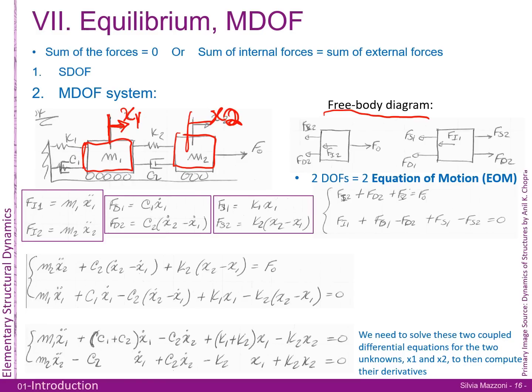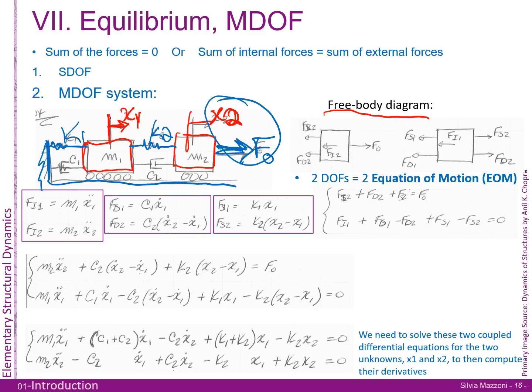Now, in this example, we've got a number of different springs and dashpots. So we have a rigid wall, very important, and then we've got a spring here between this mass and the wall, and a spring here that connects the two masses, okay? And they've got different spring coefficients, of course, because that would be too easy. And the same thing with the dashpot, okay? Makes it a lot easier because we can solve for K's, then we can do the same thing with our dashpots. And then we have an external force, F0. This force is only applied at this degree of freedom, and there are no forces applied here. You may see examples where you actually have a force at this degree of freedom, okay? But we don't in this example.